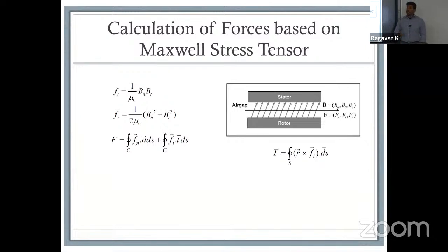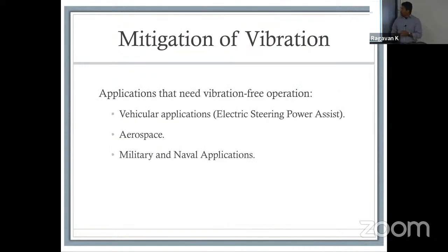On the other hand, what you can do is create a system where you give it a weight function and you optimize it for a specific criteria, because your application has a limit that you are trying to meet, which means there's a certain amount of normal forces that you are able to withstand or allow in your system. And based on that, you can calculate what the torque is going to be. So torque is given as R cross F. We know that. This is basically the radius times the tangential force. So you can calculate the overall force, look at the field distribution, define the individual field components, and from there start your optimization.